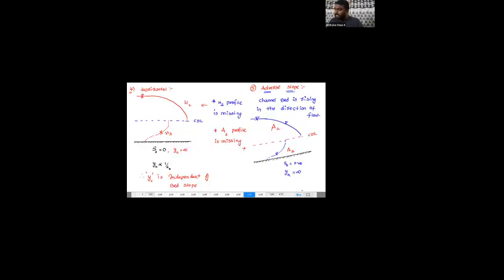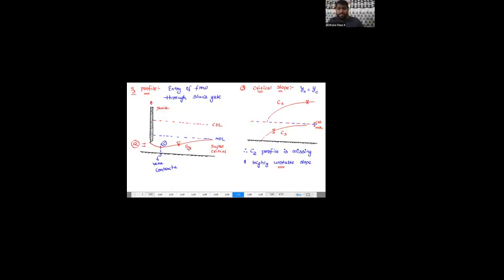As it is in an M3 profile, here the flow should meet from super to subcritical. There is a hydraulic jump. Yes or no? But if you look at the S3, is there any hydraulic jump? No. So on the downstream side of a hydraulic structure, does the hydraulic jump occur if it is a mild slope or steep slope?